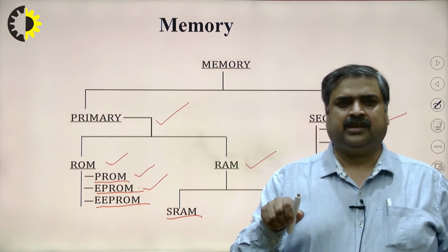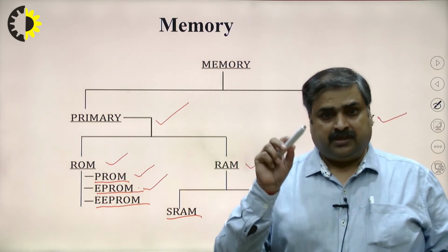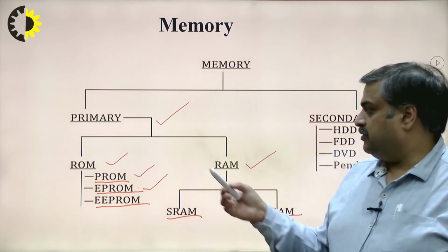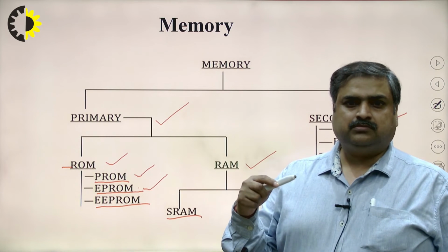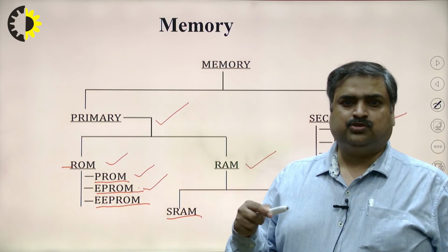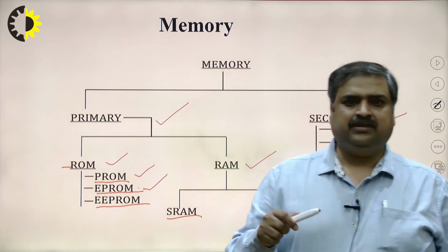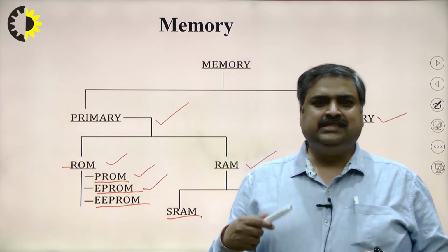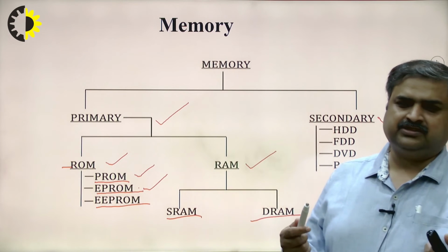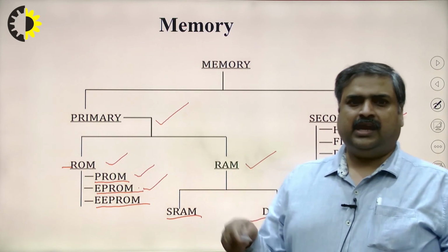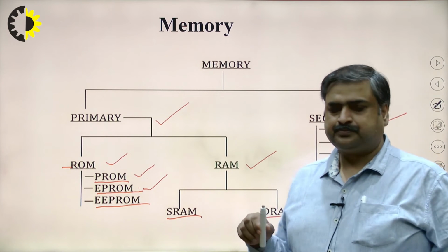So the processor cannot access this secondary memory directly. Instead, it uses the content of ROM, and ROM's instructions are used to perform a check of peripheral devices and then load the initial functions of the operating system, and those initial functions then take control and start loading the operating system from secondary memory.